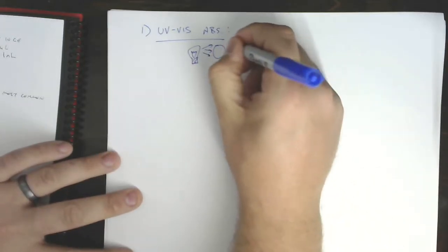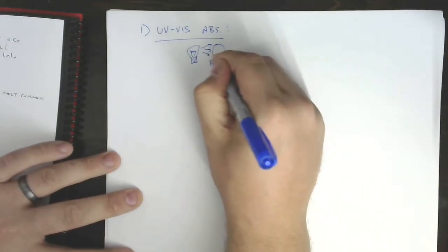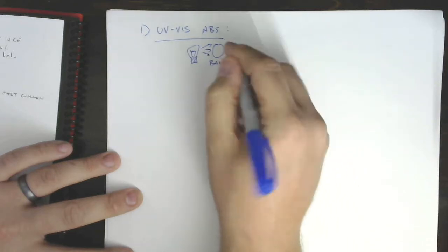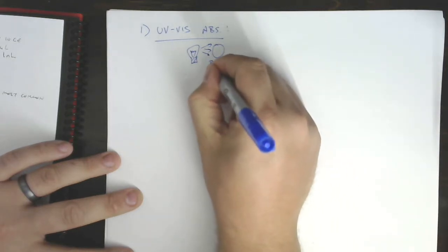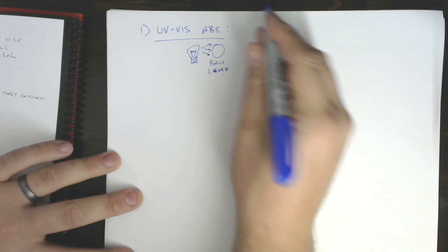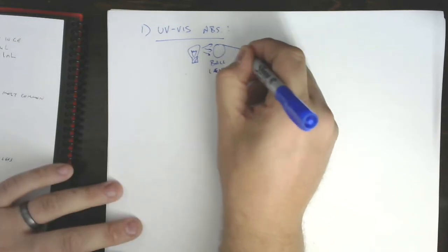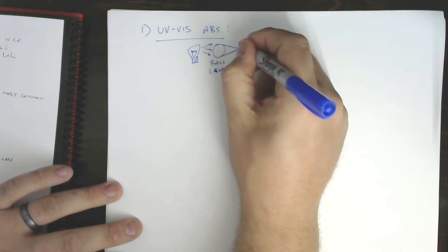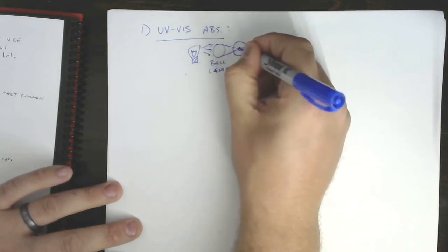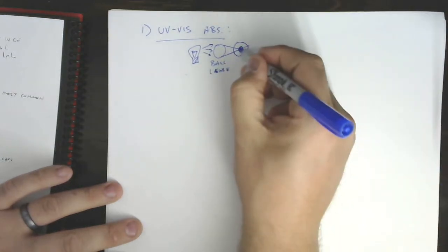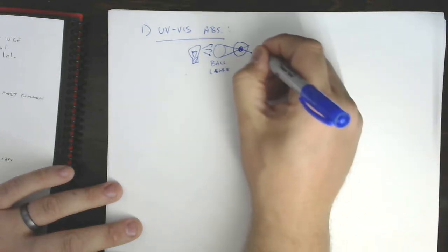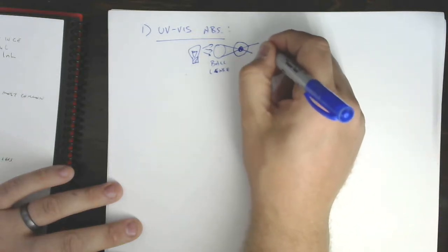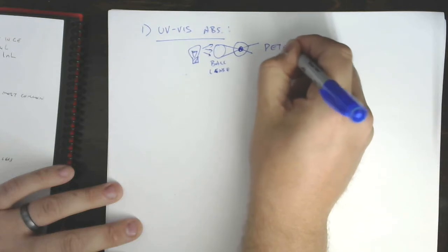You're going to couple that light via a lens with a very small focal distance. This is a ball lens. It's literally what it sounds like, a sphere of glass. It's going to bend that light at a pretty sharp angle so that it can all intersect with the capillary. This is the capillary coming out of the plane of the paper. There's our fluid, the inner diameter where fluid can reside. And that will all become incident on some kind of detector.